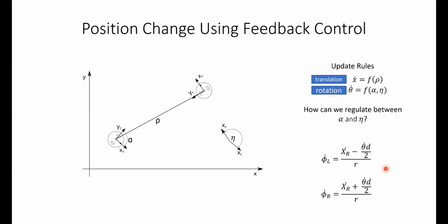So let's say I take my theta dot and I multiply my bearing error by 1,000. So now, if I had to, let's say, turn maybe pi over 2 radians, that gets scaled up. So now my robot's going to think, hey, I have to turn 500 radians for my rotation error. And if I put that into these equations, then that's probably going to drown out any translation error that's there, right? Assuming I don't put an equally large coefficient on this.